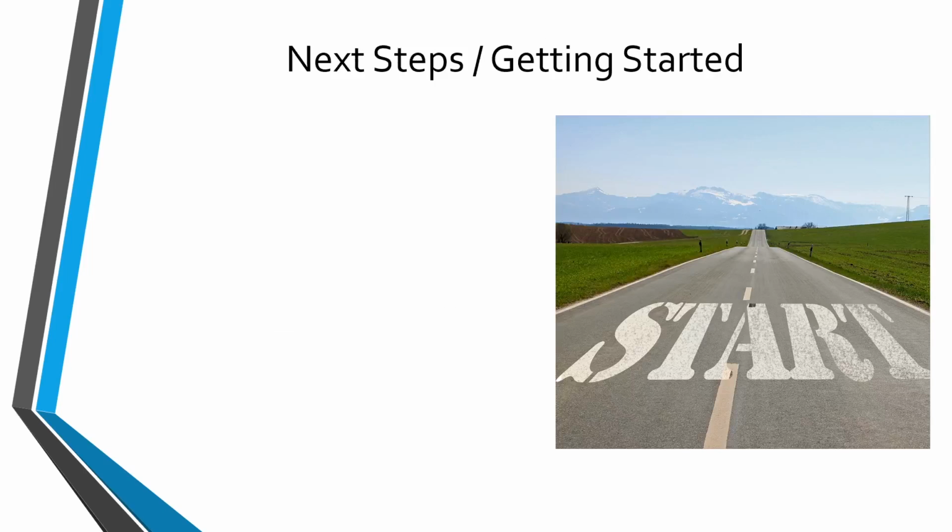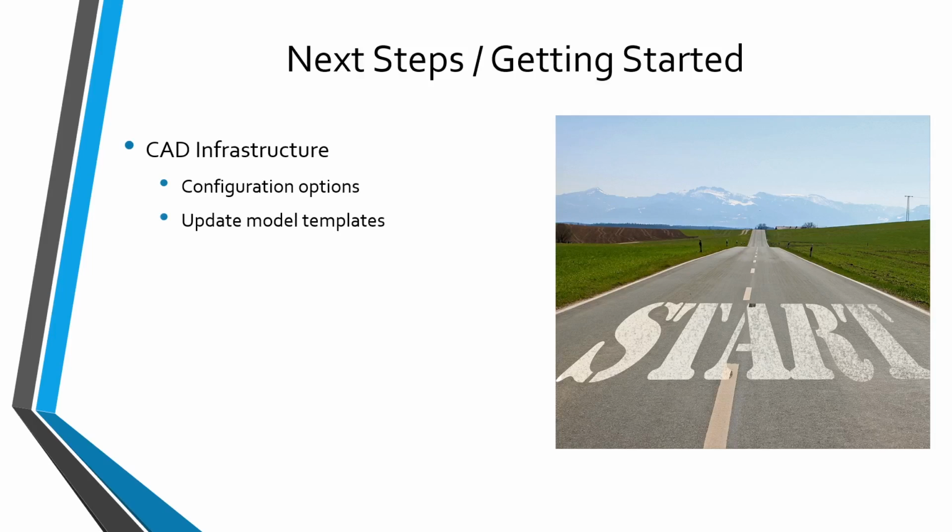All right, so let's say that you are completely drawing centric and you want to get started on your journey to model-based definition to see some of the benefits that NIST has found in that report that they generated. Well, step number one, you're probably going to have to make some updates to your CAD infrastructure. There are a few configuration options that you might want to have turned on in your company-wide config.pro, like display_combined_views. And there's some other different ones like what type of MBD you're using. And you can find out that information from the PTC spreadsheet with all the different configuration options.